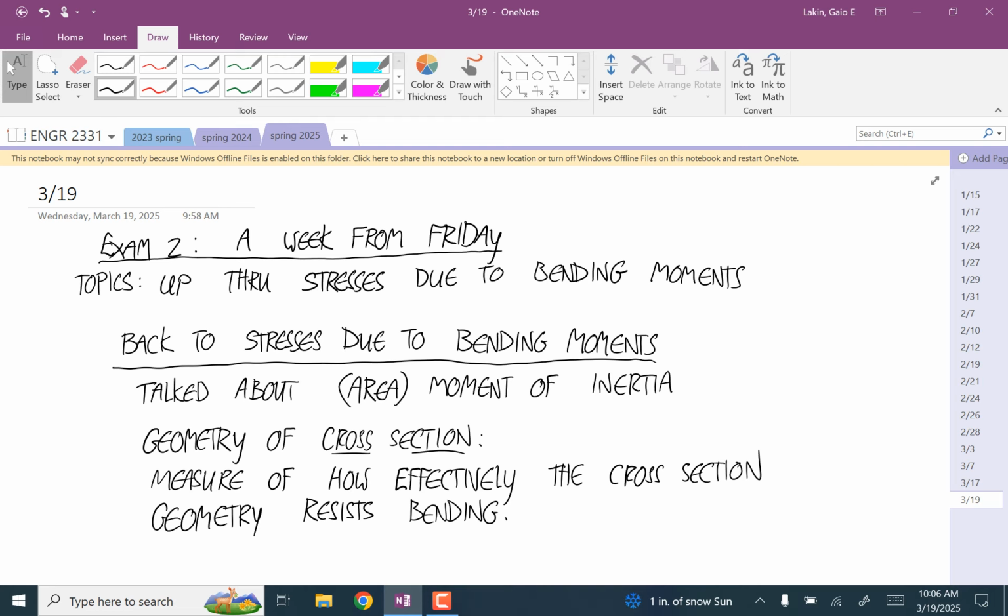And you see that on, so the beams for the 35W bridge over the Mississippi River were like 9 feet tall. Right, so if you know the direction that something's going to bend, that you're worried about it bending, then you just want to make that as tall as possible to resist that, and you're not too worried about the width.